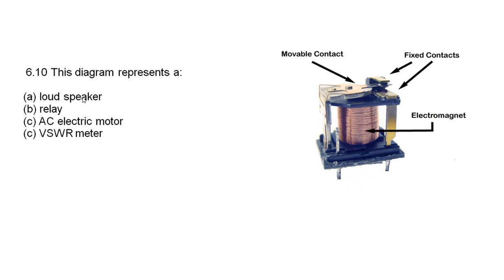And of course the device is a relay, and it was also invented by none other than Joseph Henry. He invented the relay for the telegraph because once you ran the telegraph line more than about 10 kilometres, the resistance of the wire became too great. So after about 10k at the top of the pole, they would put a relay and a battery, and that relay and battery would be operated by the line prior to it, and switch in a new battery to boost up the voltage of the Morse code signal. So every few kilometres up a pole you'd find a relay and a battery, which would have to be changed of course, to extend the distance over which the telegraph could operate.